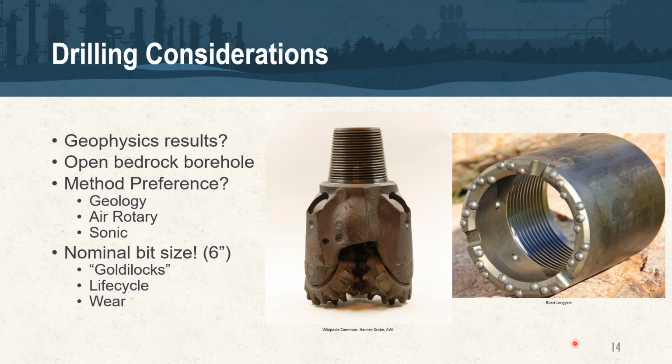So some preferences for installing these wells typically are personal to your geologist or engineer. In the part of the country that I typically operate in, we find a lot of air rotary installs, so I'm obviously deferential to that technology. It definitely makes a nice clean borehole you can easily blow out. But other places, people are using sonic, whether it's for coring or installation as well, and that works just fine. I know Bill has some experience with that, which he can talk to as well. But for me, getting a nice clean air rotary hole that's available to me for geophysical characterization is extremely important.